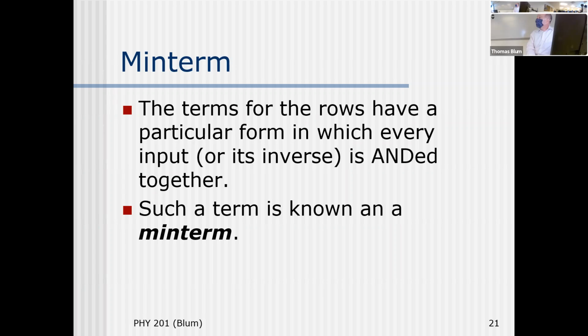Minterm definitely means not simplified. Minterm means I take all my inputs and I may prime them and then I AND them and then I OR them together. So sometimes I will ask you for the Minterm and sometimes I will ask you for the sum of products. And if you simplify, strictly speaking, you're not doing the Minterm. So if I ask you for the Minterm and you simplify, you think you're giving me a better answer and you're actually giving me the wrong answer. Probably won't mark it wrong, but I would, but it is, strictly speaking, wrong. Minterm is like just everything appears in every term.